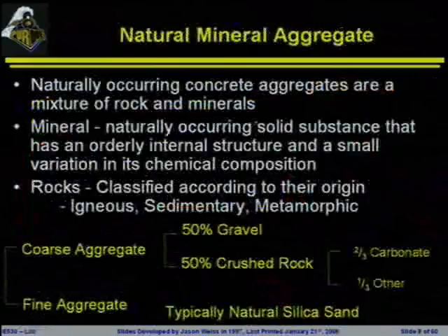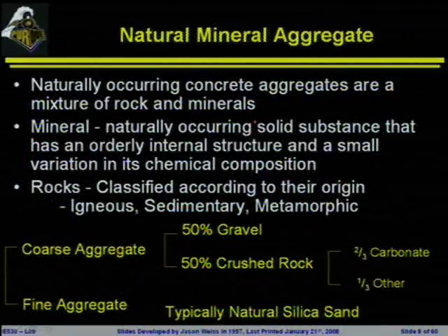forward. These are naturally occurring rocks and minerals. Obviously, you've got different types of rocks, igneous, sedimentary, metamorphic, and we will look at, as we go through, each one of these has its own issues when we start to talk about durability and we start to talk about other processes inside of concrete.